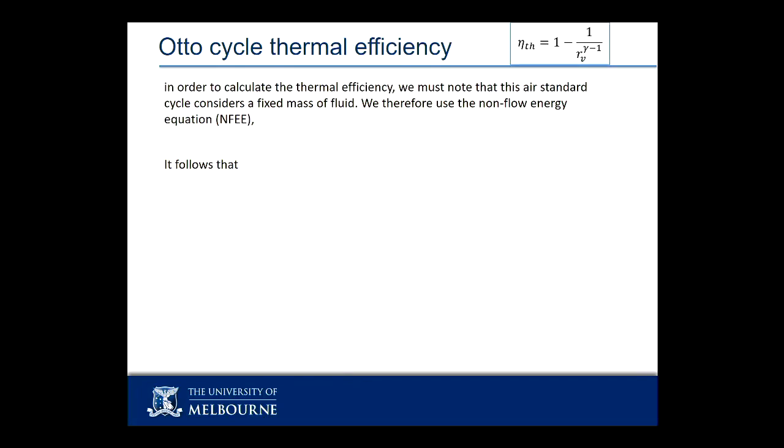Okay. We'll play the same game, which is to say let's get an expression for the efficiency. This time, the energy counter that I'm using, as I said before, the energy counter I'm using for a closed problem is internal energy. And so if I'm using internal energy, then I get to use CV delta T, not CP delta T. That's your job to remember.